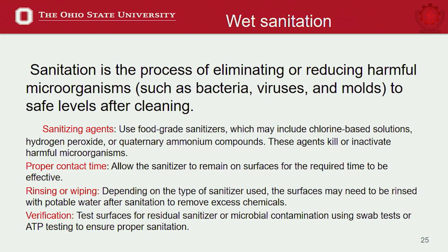What is dry sanitation? There are instances where in a food processing plant you may be processing a number of dry ingredients, like flour, milk powder, things like that, where you do not want to use water, because in those dry processing environments, if you use water, it can hide in small niches and crevices, and if a lot of powder deposits there, it serves as a source for microorganisms to grow and cause a problem.